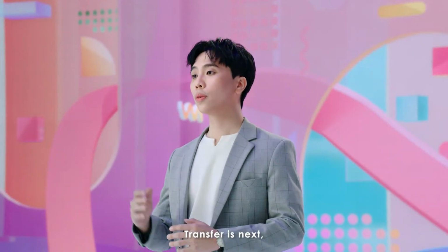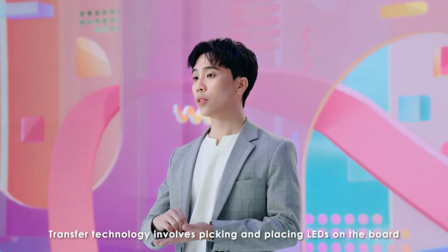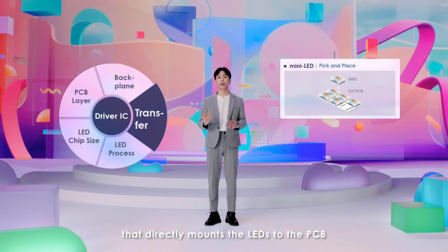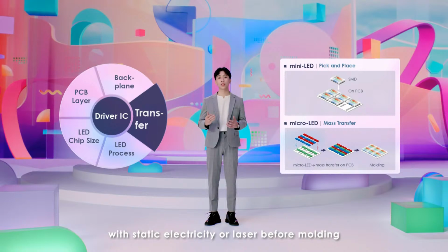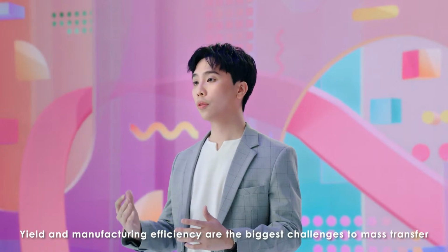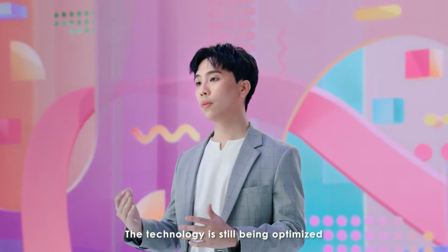Transfer is next. Transfer technology involves picking and placing LEDs on the board. Many LEDs generally use traditional pick-and-place technology that directly mounts the LEDs to the PCB. Mass transfer puts LEDs on the PCB with static electricity or laser before molding. Yield and manufacturing efficiency are the biggest challenges to mass transfer. The technology is still being optimized.